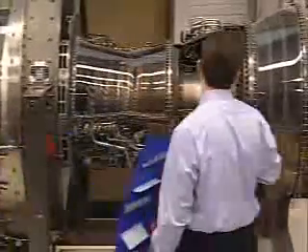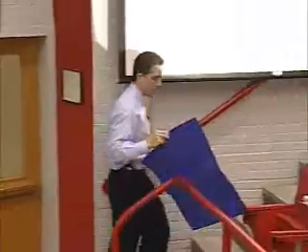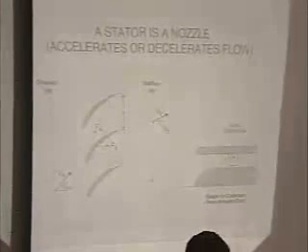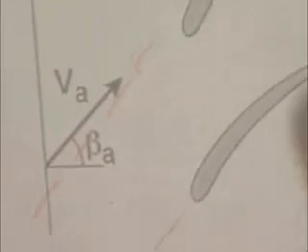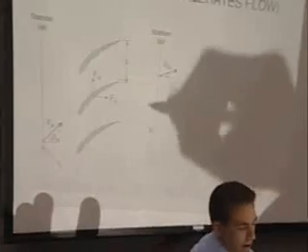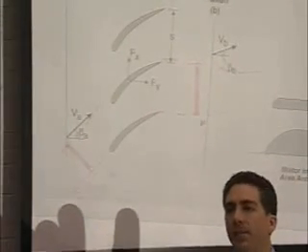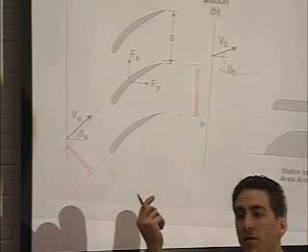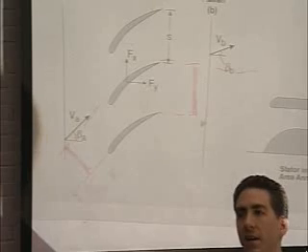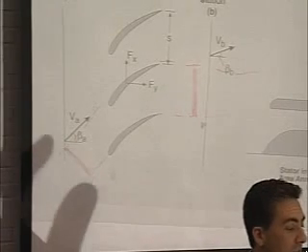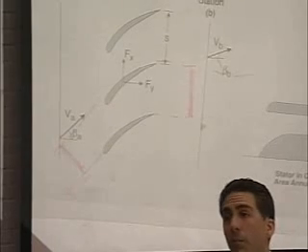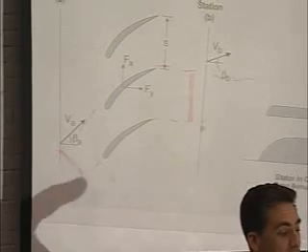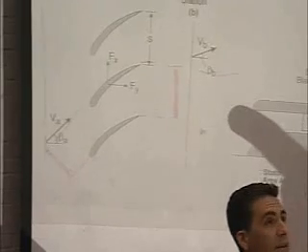Right, so that's just a general problem. But the way that this then converts kinetic energy into internal energy, if you remember this, is that the flow area coming into this was different, right? So you have a perpendicular distance across this pipe and a perpendicular distance across that pipe coming out, and they're different thickness pipes. So it's just like a nozzle. A nozzle takes internal energy and converts it to kinetic energy. This does the same thing. You've got a small pipe, if you think about it, that gets to be a big pipe. Converts kinetic energy, lower speed flow, to higher internal energy at the exit.